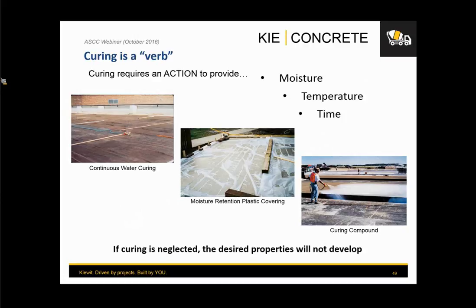Yeah, well, the curing aspect is all about also the application and exposure. For example, what are you trying to achieve with curing? It is basically to avoid the concrete getting rapid drying from the surface. If you're dealing with a pavement or a bridge deck that is going to be exposed to a lot of de-icing chemicals in the northern part of the U.S., right? Then obviously you're going to want to have some additional water being applied on the surface, right? Because you want to make sure that material receives proper hydration and hydrates pretty well on the top of the surface.